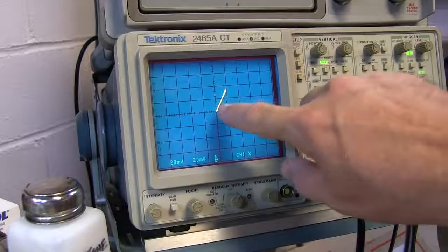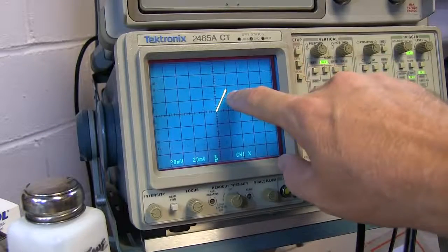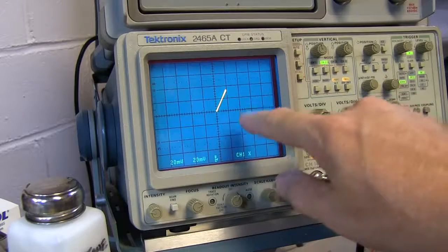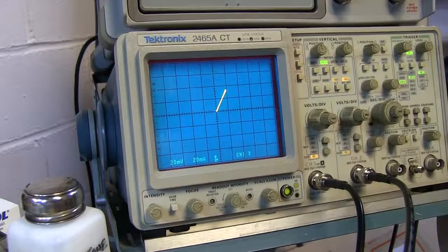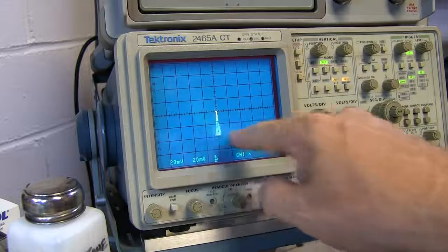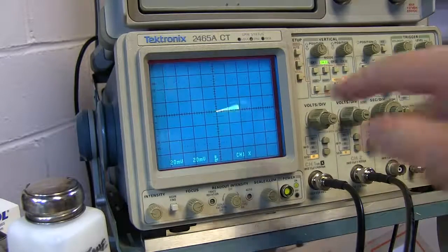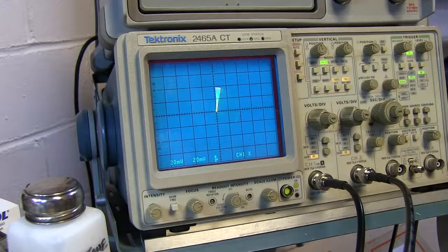So again, here's our amplitude modulated signal basically phase locked to the LOs. What I'm going to do is now introduce a 1 hertz frequency difference between my modulated RF signal and the IQ signals, the LO signals. And you can see what I'm doing is causing that phasor to rotate at a once per second rate. That's because we have a 1 hertz frequency difference between my quadrature local oscillators and the RF signal.